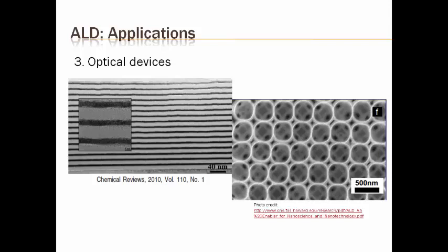This photonic crystal was made in the following process. A crystal array of silica spheres was fabricated. Tantalum oxide was deposited between the spheres by ALD. This was converted to tantalum nitride in presence of ammonia. The silica spheres were dissolved in hydrofluoric acid to leave behind this beautiful photonic crystal structure. Similar principles have also been used in biomedical applications to get an intricate exoskeletal model of an insect to be researched on.